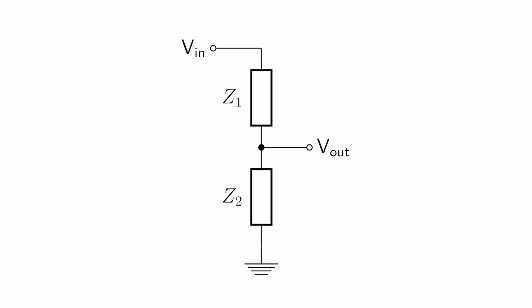To summarize, the voltage divider rule is a simple way to calculate potential differences across resistors in series. This rule saves time and simplifies calculations as it does not require the use of current or other additional calculations. A basic application of the rule is the voltage divider circuit, used to generate a part of its input voltage as an output with minimal components. But there are many more uses for this handy rule, so there you go.